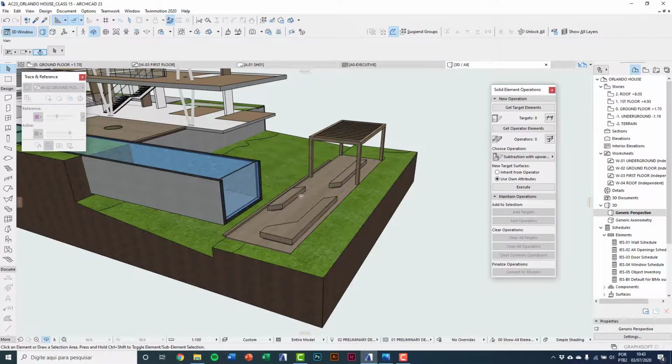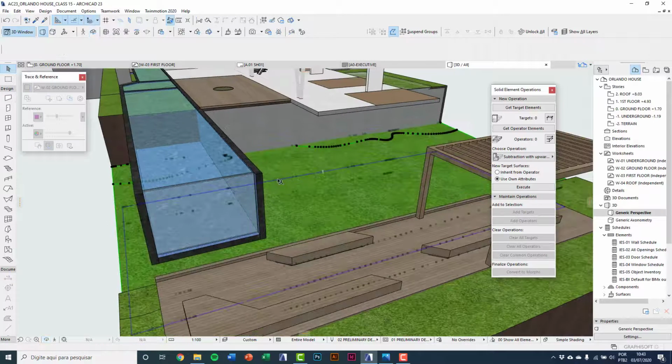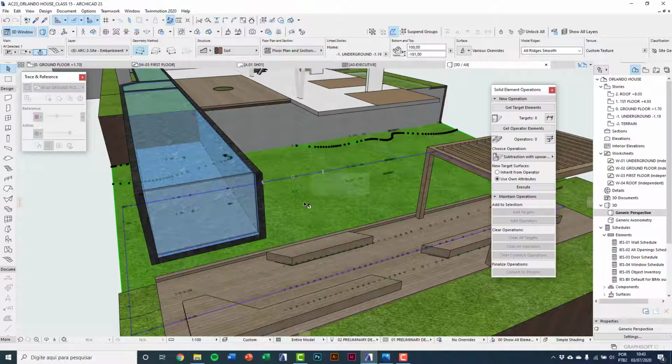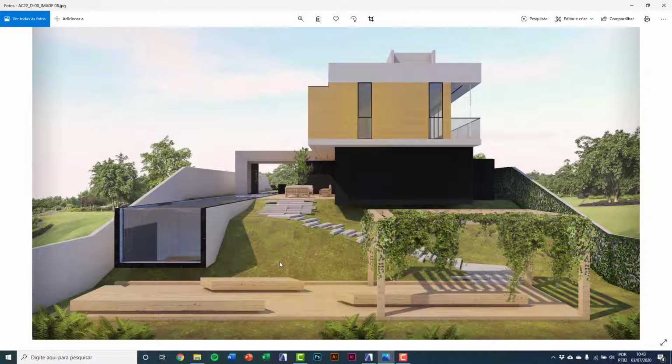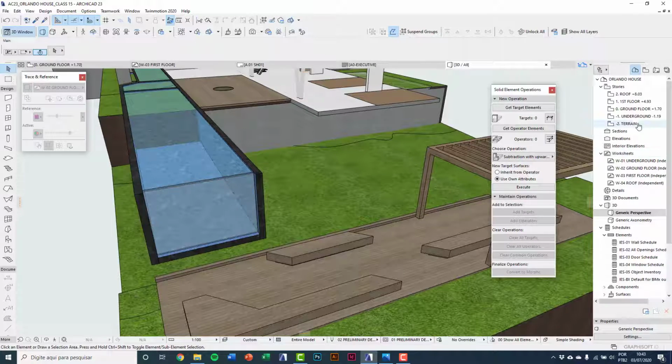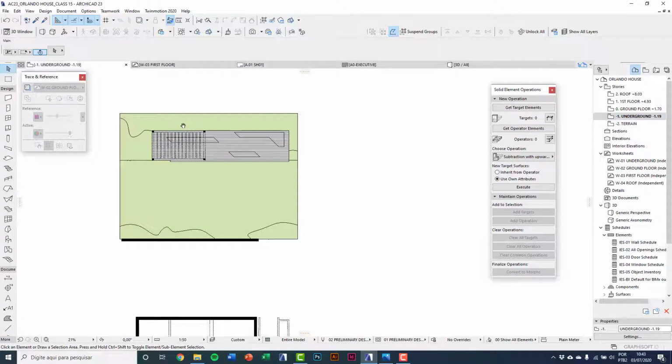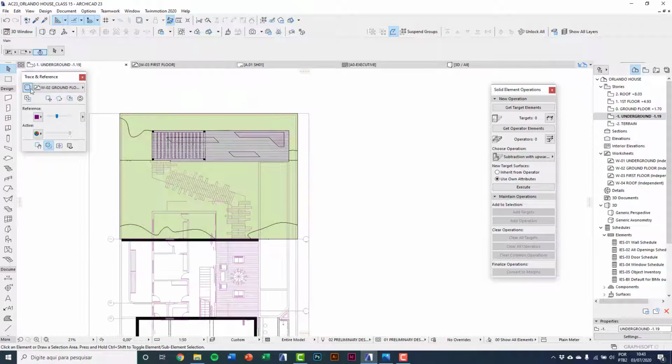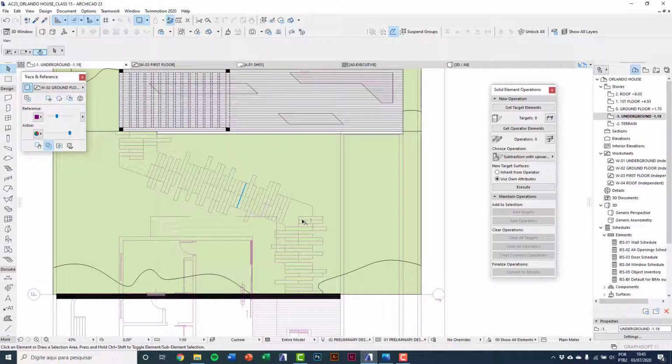Now I'll make the sloped grass in this area. And it has some variations according to the concrete path, as we can observe on images. In the beginning, we have a smooth slope, and after a stronger slope. In underground, I'll place DWG reference from ground floor, where we have the view of this concrete stair as reference.